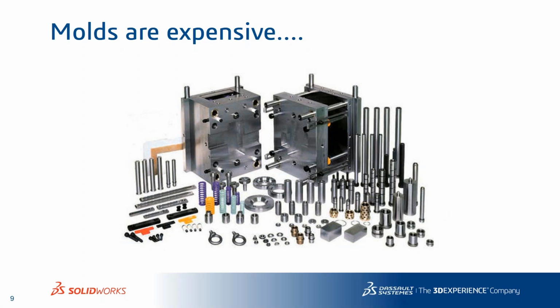As you could see, that mold is a typical mold, and I wouldn't even consider it a big one. This is what's involved in making a mold. You have injector pins and sliders and springs and sprues, and that doesn't even show you the core and cavity and how complex that can be. It took 5 weeks to modify that mold, which is probably about half the size of the one we used for the flashlight, to get it to where it could shoot that part again without those sink marks. So it was expensive. It cost us a lot more money to fix it. And it almost killed our whole deal of selling it by not being able to get it to the show.